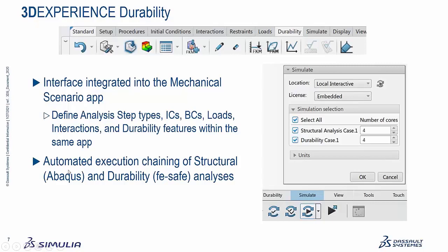So you can set up all your structural analyses, use them as many as you like to drive as many durability cases as you like, and then you just click OK here, and it'll automatically chain all of the structural simulations and the durability analyses.